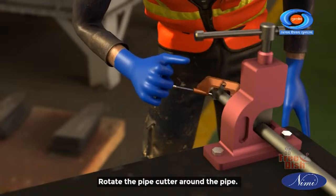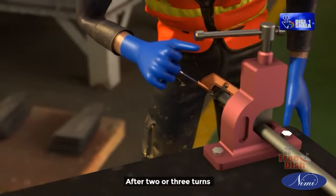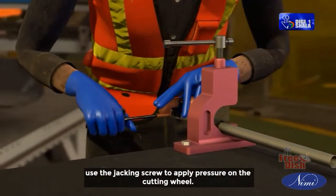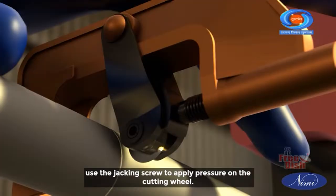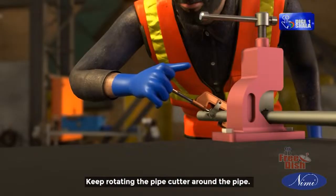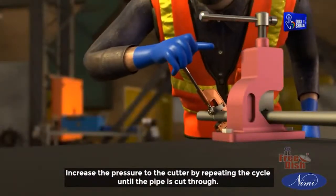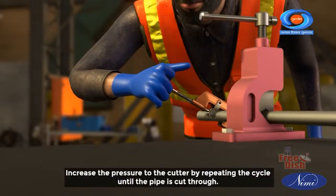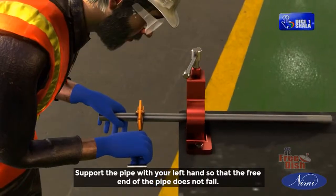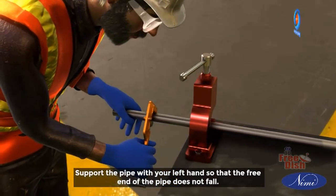Rotate the pipe cutter around the pipe. After 2 or 3 turns, use the jacking screw to apply pressure on the cutting wheel. Keep rotating the pipe cutter around the pipe. Increase the pressure on the cutter by repeating the cycle until the pipe is cut through. Support the pipe with your left hand so that the free end of the pipe does not fall.